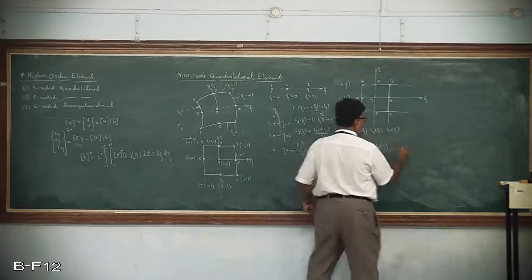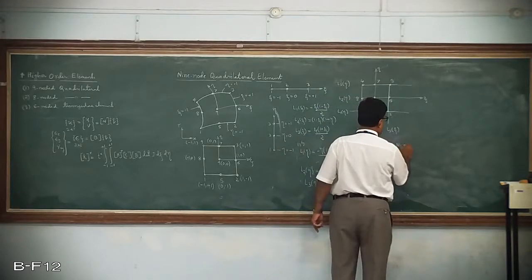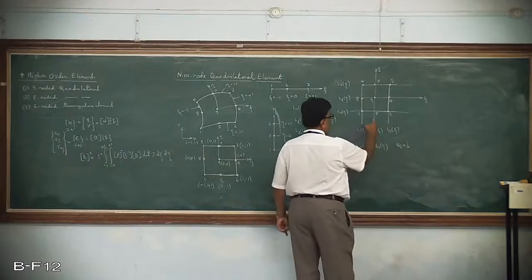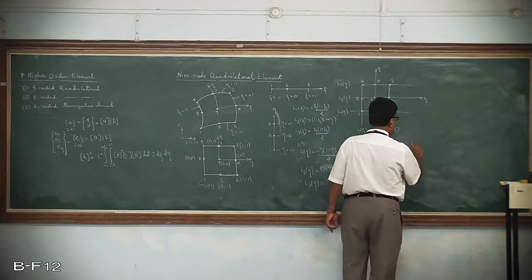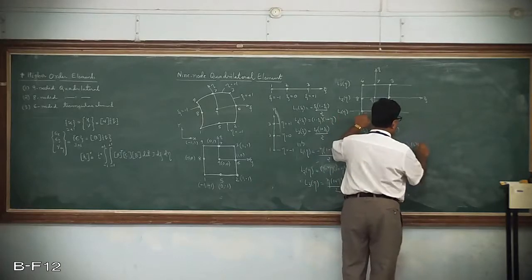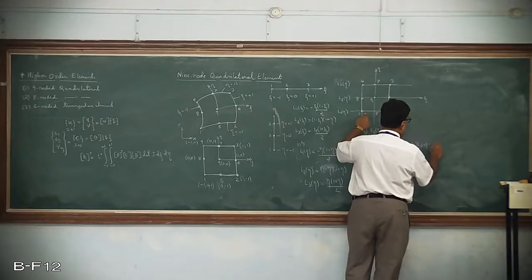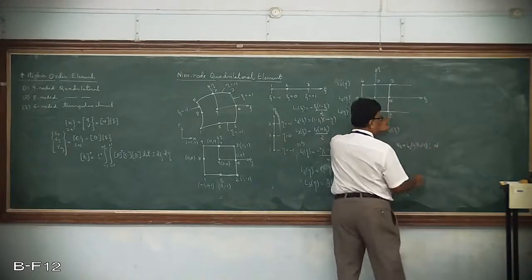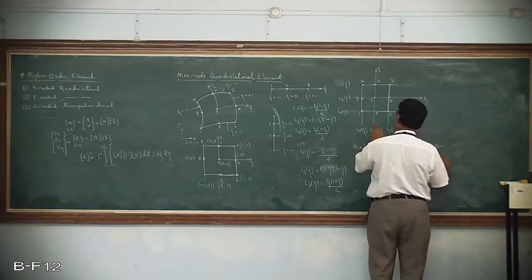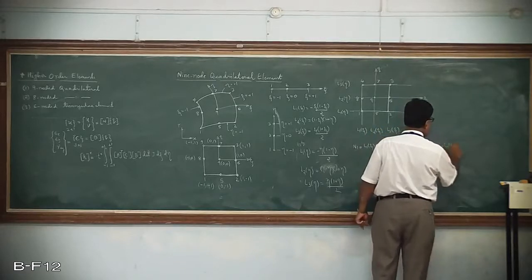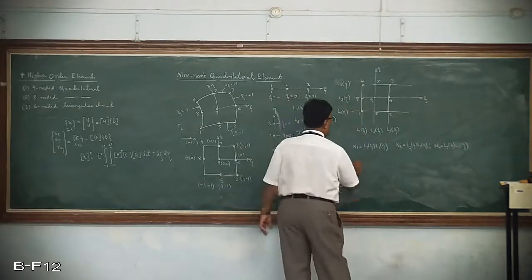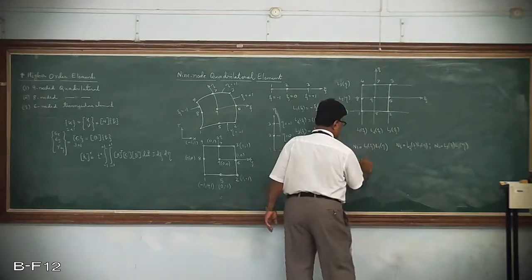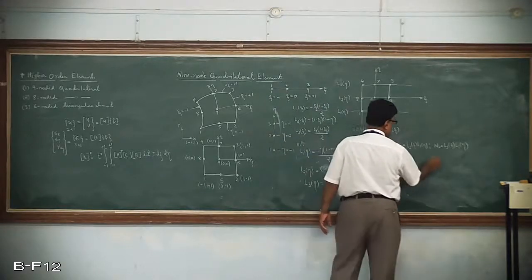Next comes N5. What is this? It is the product of, again, L2 of zeta here, but since it is on the same line, L1 of eta only will come. Similarly, if I want the last one, that is N2, what is N2? It is going to be L3 of zeta into L1 of eta only. Next, when you come to the horizontal line, it is N8, N9 and N6.